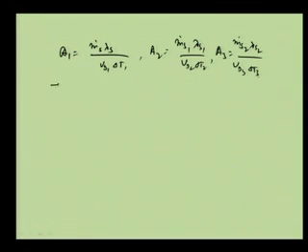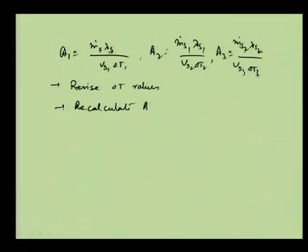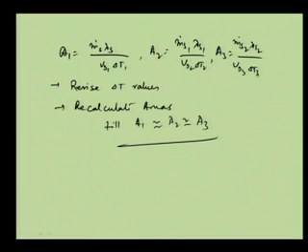If not, then revise delta T values, recalculate areas, till A1 is nearly equal to A2 is nearly equal to A3. So, this is the basic objective, the basic way of doing the heat exchanger design. Now, not heat exchanger, evaporator design.